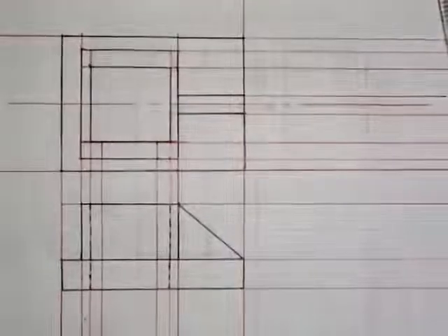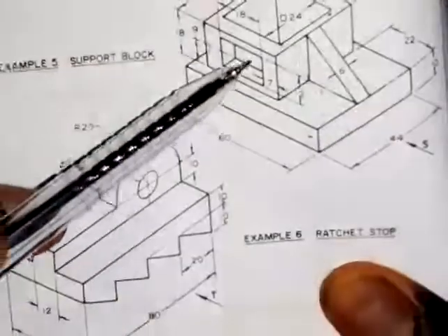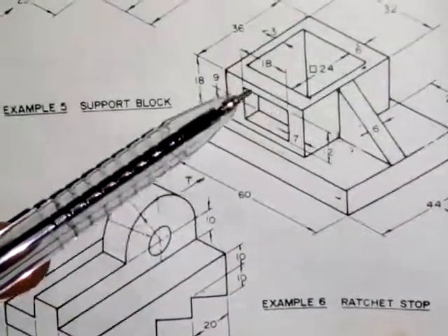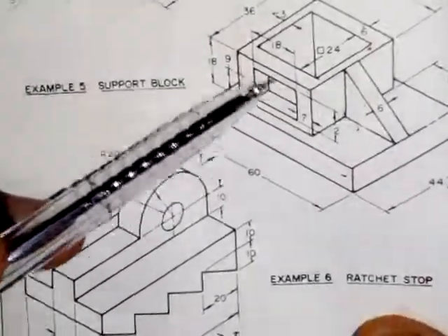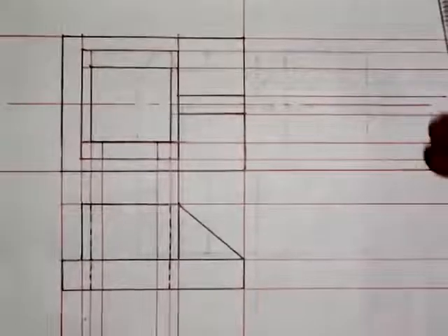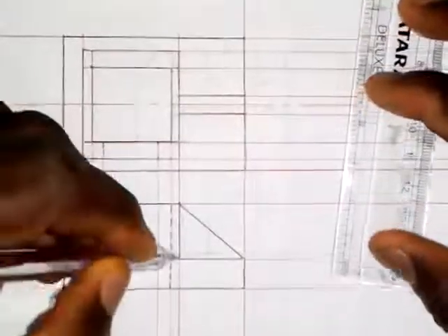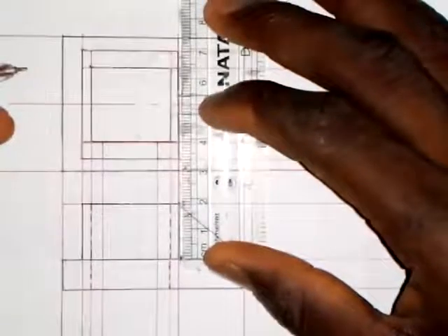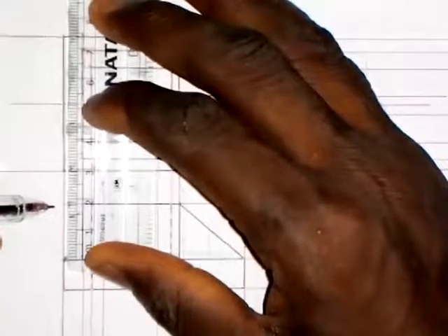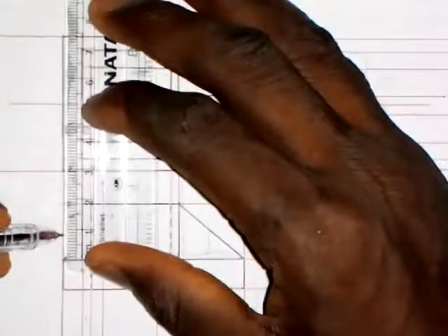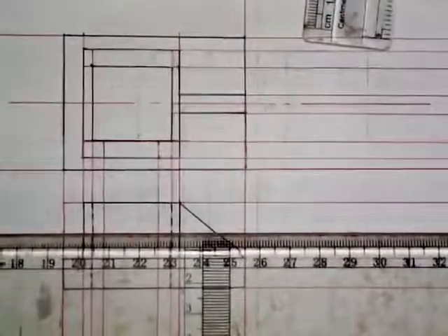All right, so the next thing that I'm going to do is put this rectangle on the surface of the front elevation. I want to put it there. So I need to divide: the distance from here to here is 18 millimeters. So I will divide that 18 into 2. That is 9 millimeters. It is even given to us in the diagram itself. So this is 9 millimeters here. So I will draw a horizontal center line from here.